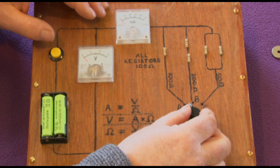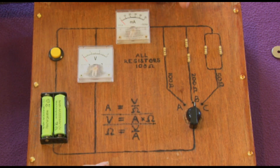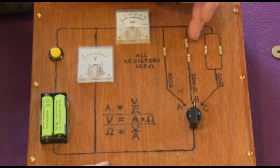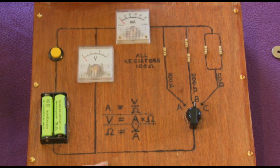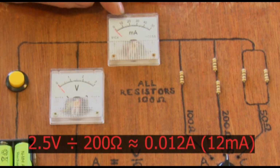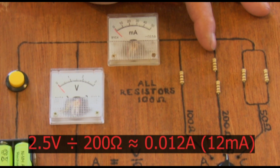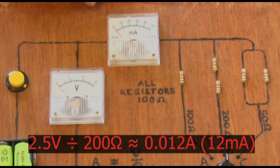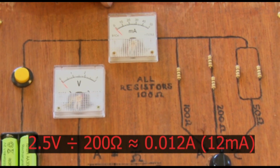Now, if we move this across to the second option, option B, we've got two 100 ohm resistors, and because they are in series, the total resistance we get from the two of them is 200 ohms. So when I press the button this time, we're getting half the current. We're getting about 12 or so milliamps, and if we take 2.5 and divide that by 200, we get 0.012 amps or 12 milliamps.